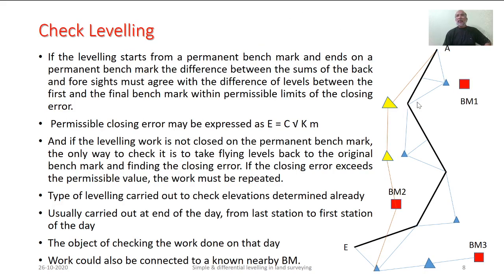Here, say we started our leveling work from station A, with respect to a certain benchmark. The blue triangles represent instrument station 1, instrument station 2, 3, 4 and accordingly.